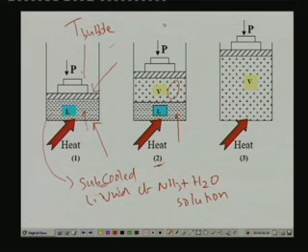That means at a particular temperature, let me call it as T dew point. Okay. The last liquid droplet evaporates. Further heating will simply result in superheating of the vapor. Okay. So, here you have vapor, here you have as I said the subcooled liquid, and here you have a two phase mixture consisting of vapor and liquid.